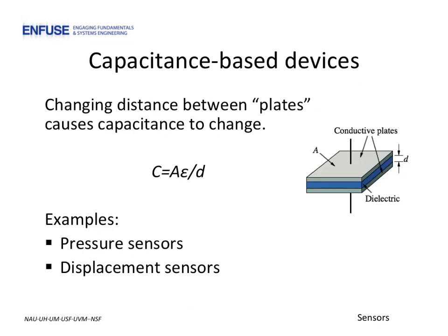From your study of capacitors, you know that an ideal capacitor can be modeled as two parallel conductive plates of area A that are separated by a dielectric of thickness d. The capacitance can thus be calculated using this equation. If one designs a sensing device in which the distance between the plates is altered with a phenomenon, for example force, then the device's capacitance will also change. One can also design a sensor in which the dielectric constant changes with the phenomenon. This is the principle upon which many humidity sensor designs are based.